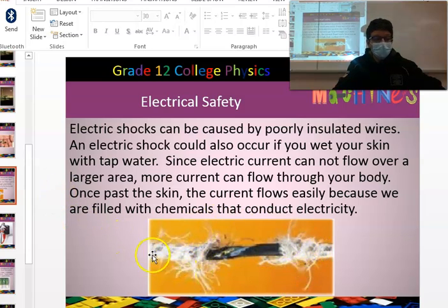And to prevent that from happening, you need to be a little bit self-aware. A wire like this, you should never be using. That's an exposed wire. There's a reason we have that outer layer on a wire. It's an insulating layer, so that if you were to touch any normal wire, you're only touching the insulating layer. You're not actually touching the metal that you have a current running through. This, you could actually touch that metal. And if you do, that electricity will choose to go through you.